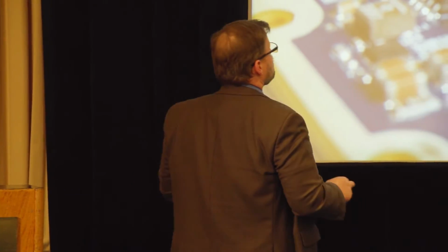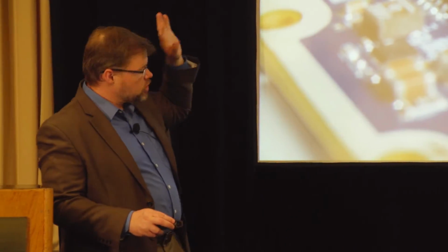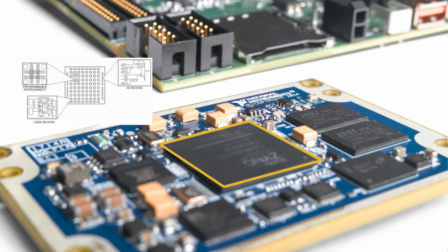Okay, here we go. Now I already talked about what an FPGA is. This visual was intended. That's a Xilinx part called Zynq. It's an SoC that's got an FPGA on it as well as a processor. But sometimes people think about FPGAs as just simply being logic and interconnects. They've really evolved. Contemporary FPGAs do have hard DSPs on the FPGAs themselves that can handle floating point data pretty well. And then there's a bunch of interconnects and logic that are running in this dedicated piece of hardware.